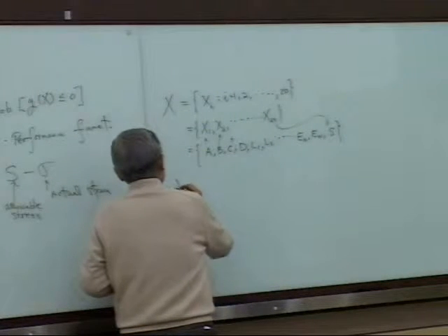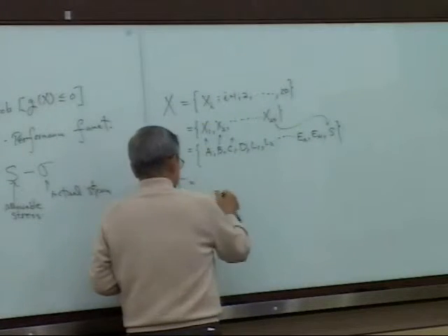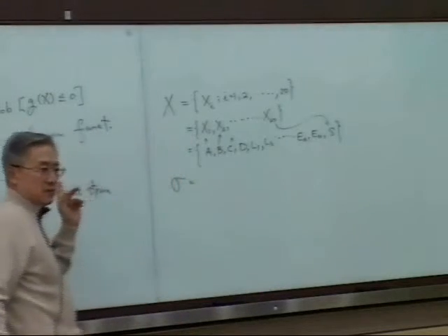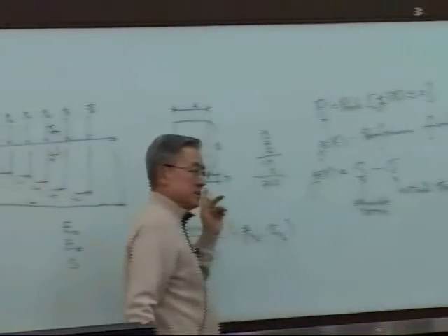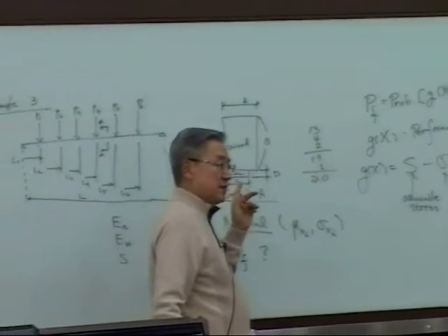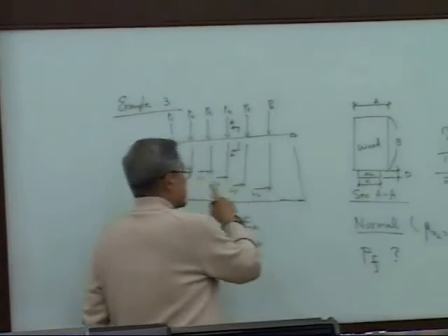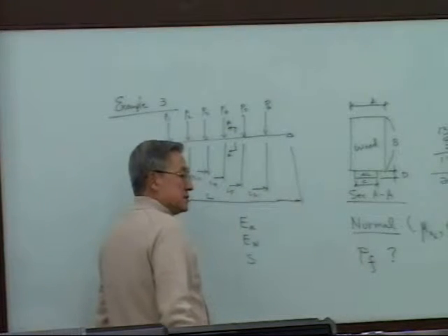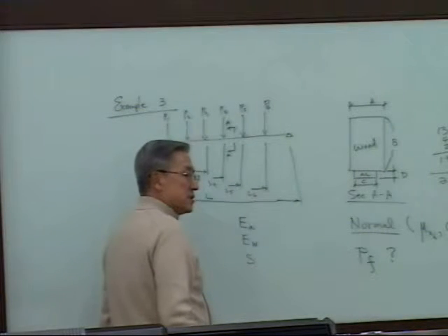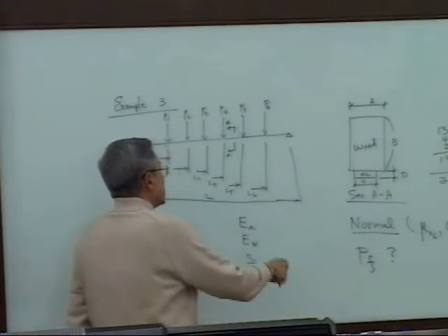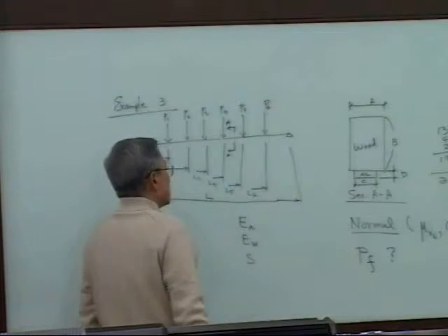And where could the maximum stress occur in this situation? At the center, right? This is symmetric loading, and the cross-sectional property is really uniform. It's not tapered or anything.